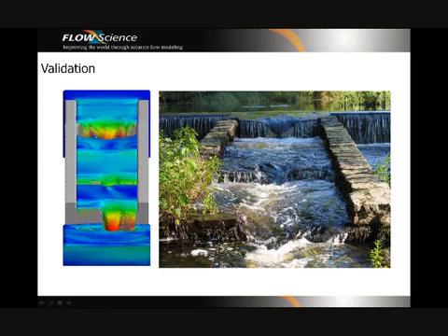As shown here, the flows of the Flow3D model matched very closely that of the observed fish ladder, providing confidence that the simulation data was accurate. This validation simulation also provided detailed information as to the velocities in any given location, helping determine where the changes in the fish ladder design should be made in order to help the alewife swim upstream.